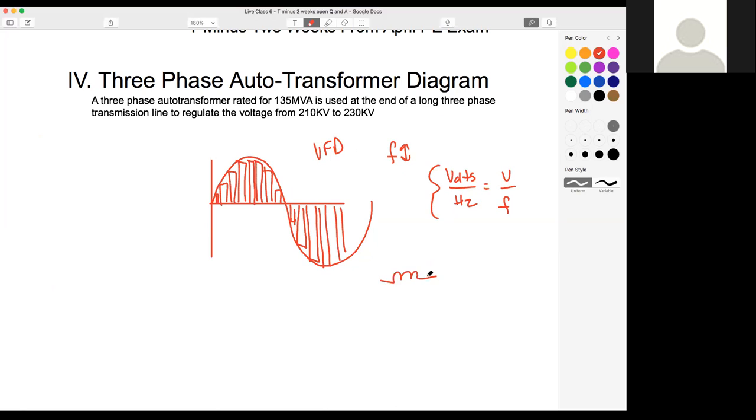When we have an inductor and it creates a magnetic field, say for the case of a motor or a transformer, if that inductor is rated in henries, if we want to get to our ohms, our X of L, then we multiply that henry by what? Omega, which is the same as 2 pi times our frequency F, times H. Does everyone see that?